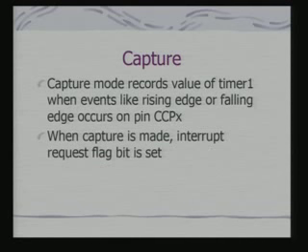Now, this is a very interesting feature. You are actually recording events, and you are recording events with respect to time. This kind of feature is not commonly available in other processors. You must not have encountered it in a general purpose processor like the 8085 or 8086. It is provided here because this is supposed to take care of various external events interfaced with the external world. So, it can keep track not only of the event, but also of the relative time based on the timer count when that event has occurred, and that value is recorded in the capture register.